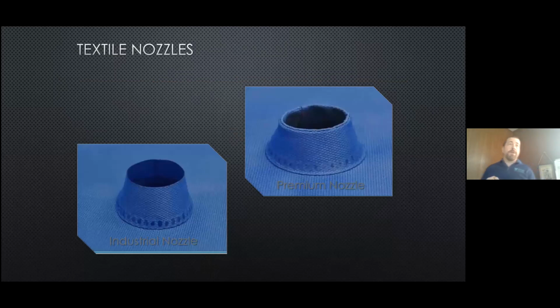Real quickly on these, a couple of different ways that we do these. For places where the aesthetics are not that big of a concern, industrial manufacturing being a great one of those, we'll use a single wall design, single wall constructed nozzle. For places where the aesthetics are important, we use a double wall construction with a little metal wire that goes around the opening to maintain that shape. The purpose of that is to eliminate any vibration from these small nozzles. It's just a very small but very customized aesthetic improvement to the systems when we start moving nozzles there.